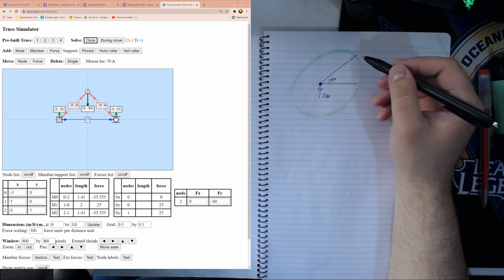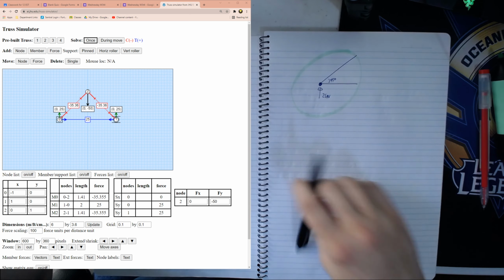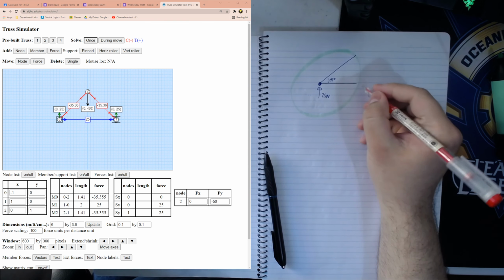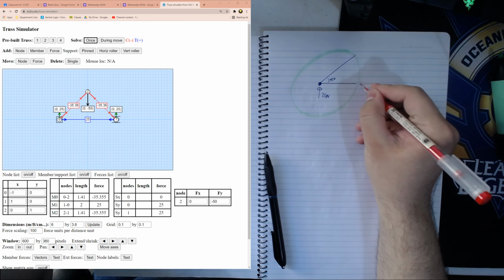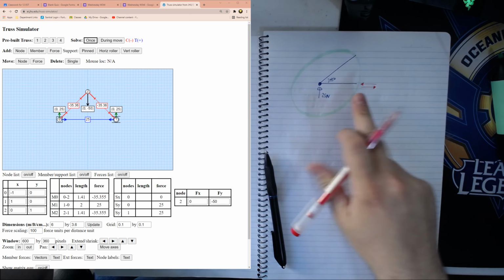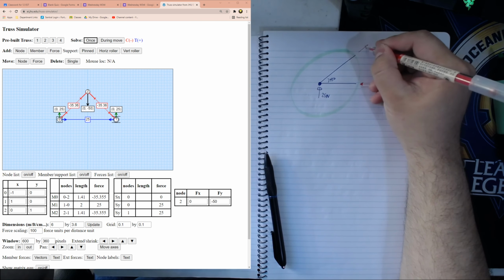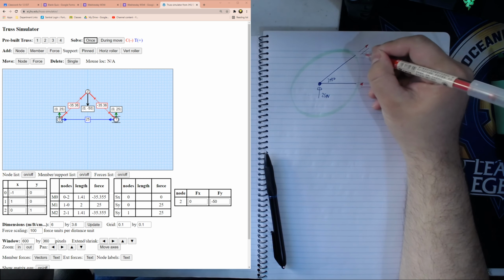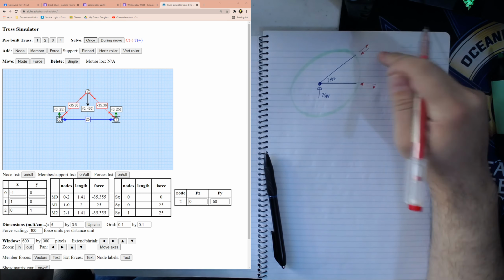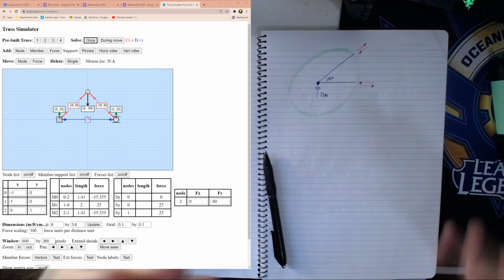But why we do our truss analysis is that one of our definitions for our nodes is that the force has to be in the direction of the member. So this one over here has to be going either to the left or to the right. This one over here has to be diagonal, either towards or away from the node. That's by the definition of the simplified case we did for our members. They can only handle the force in that direction.